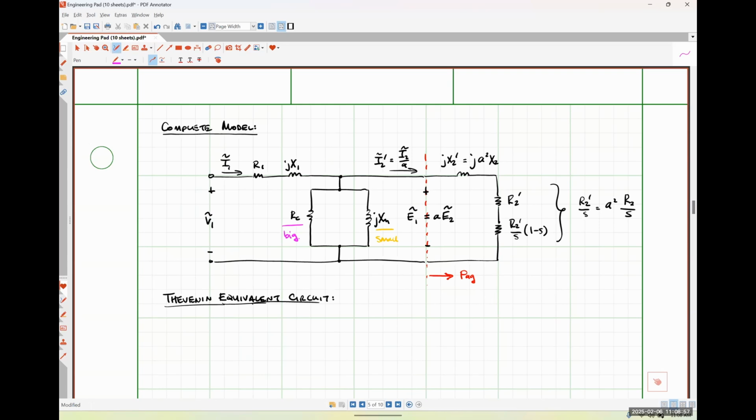So if I have, let's say, a 5 ohm resistor in parallel with a 5 kilo ohm resistor, you guys have calculators in front of you. What do I get? Pretty close to the 5, exactly right. So when I have parallel resistances, it's always going to be smaller than the smallest resistance, but if there's a huge difference between them, it's going to be just under the smallest resistance, meaning that I'm just going to lump these core losses in with something else so that I don't have to add that to my circuit anymore, okay?